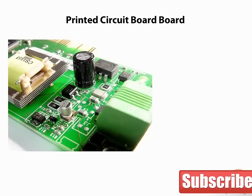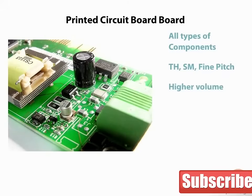Advantages to building circuits on a printed circuit board are that all types of components can be used with equal ease. Through-hole, surface mount, and fine-pitch components are easily implemented. PC boards are most suitable for commercial production. Assembly of the components on the board is done with special robots, making the cost per board very affordable at volume. You can render a complex circuit on a PCB as easily as a simple circuit, using PCB software readily available to the individual designer.